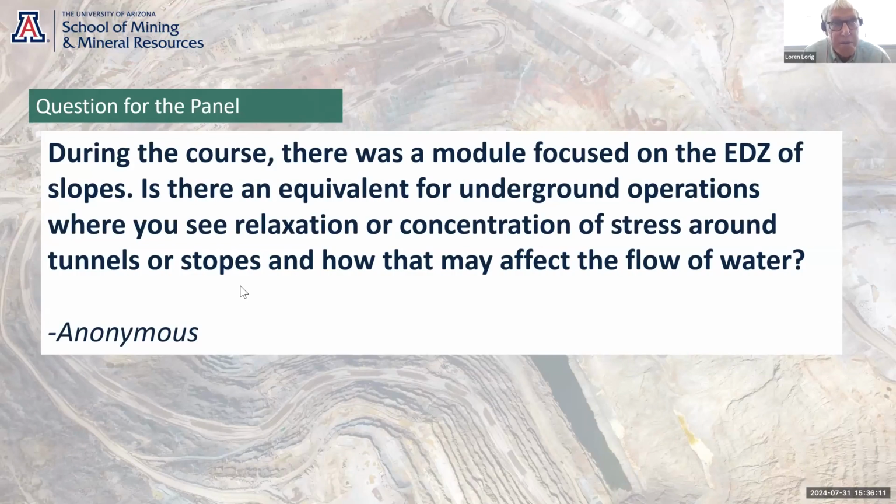And Jeff talked about in stopes with structures parallel to the stopes. There's almost no confinement, so those things can open up very easily. Structures around tunnels, particularly if they're circular or near circular, are very, very difficult for those things to open up very much, because they're so highly confined. You might get an excavation damage zone around a tunnel that's a meter or two, and in stopes we're talking about tens of meters. So that's the difference.